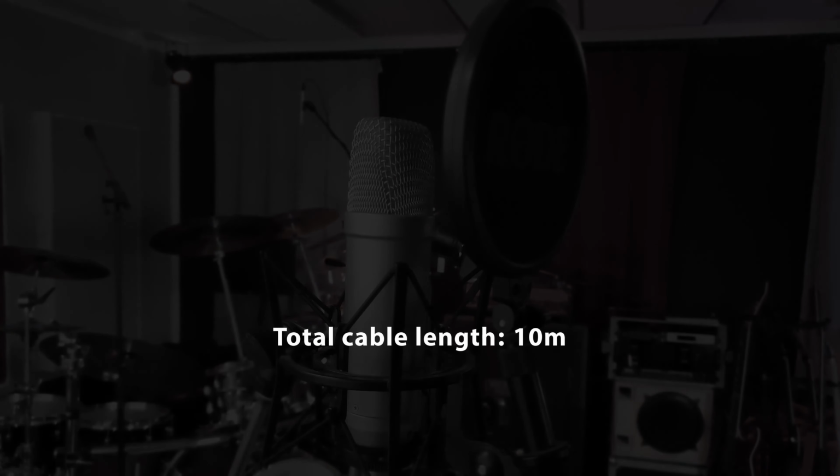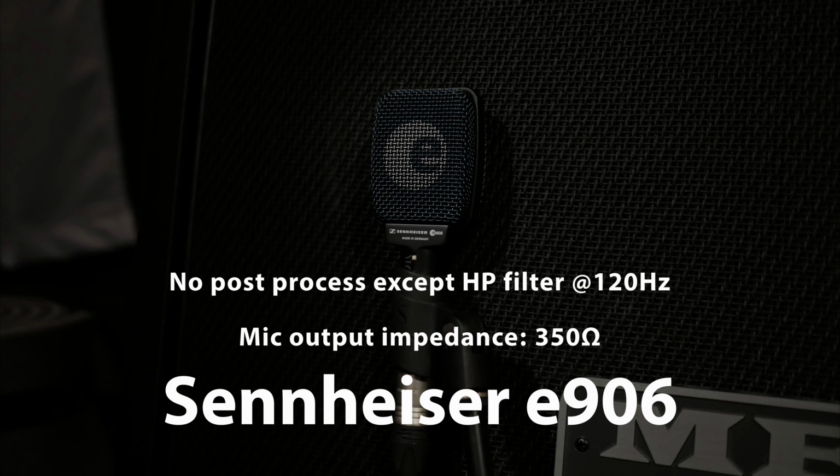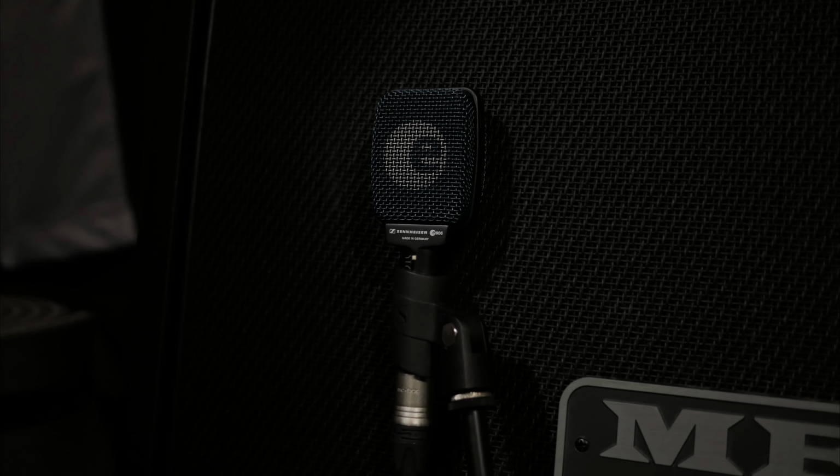Yeah. I switched to the dynamic Sennheiser E906, which is actually an instrument microphone. And I am doing the same test, so the 10 meter cable alone, directly to the Focusrite Scarlett with 3K input impedance, and the previous longer combination with only one difference, there is no phantom power. In the next sample, you'll hear passive and active guitar with 2 meter and 10 meter high quality cable with capacity of 560 picofarad and 1.27 nanofarad.